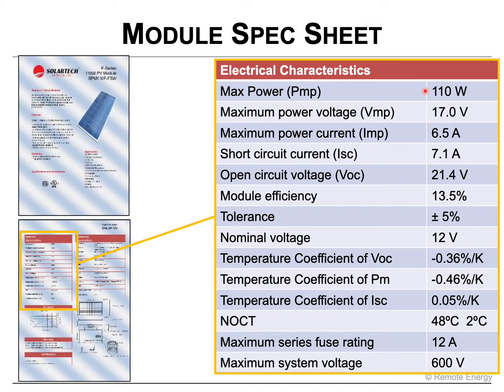That's when the circuit is running under load, this module will produce about 110 watts with this many volts and amps. They also give us two other readings. One is the short circuit current, ISC, where the I stands for intensity. They're saying that is 7.1 amps, and that would be if there was a direct short. So this is the maximum amount of current that you could ever see. You're not typically going to see this under load. This would be under a short circuit condition.